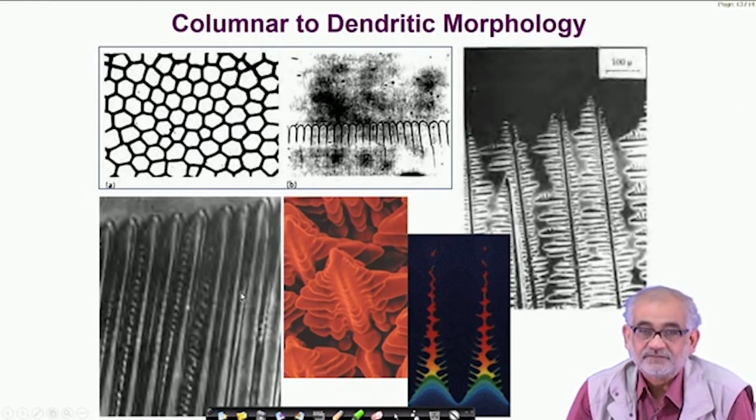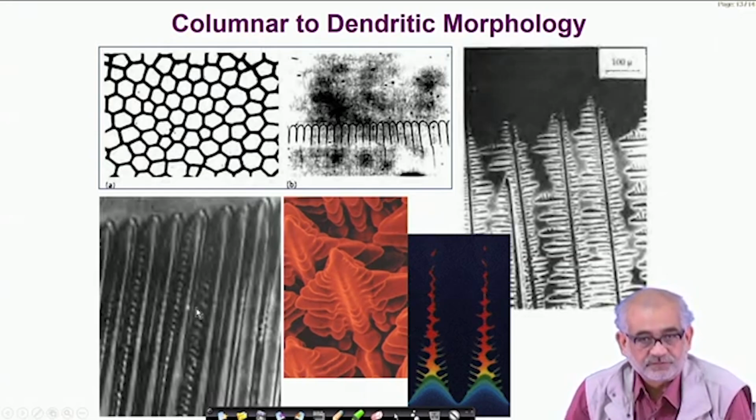But in between, from the core where we have equiaxed to the surfaces where we have chilled or ultrafine zones, we are likely to see directional solidification. And this directionality comes from the fact that heat transfer is across the mold wall, which could be the side walls or the bottom walls.